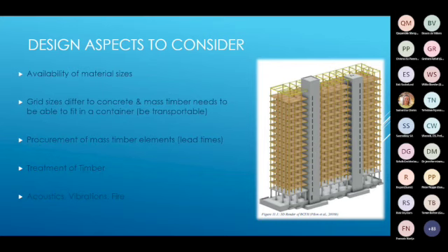In other words, timber above ground in the coastal areas needs to be treated to H3 hazard class, which is copper-based waterborne preservative. Generally, imported mass timber is untreated, making it unsuitable to use as a structural building material within coastal zones unless treated afterwards.